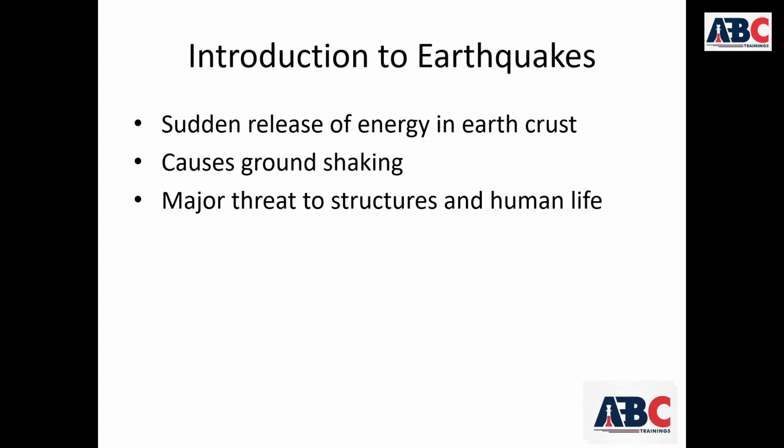Now, why is this shaking dangerous? Buildings are mainly designed to carry vertical loads like dead load and live load. But during an earthquake, the building experiences horizontal force. These lateral forces create bending stress and torsion in structural elements like beams and columns. If the structure is not designed properly, this can lead to cracks in walls, column failure, foundation damage, and complete structural collapse.